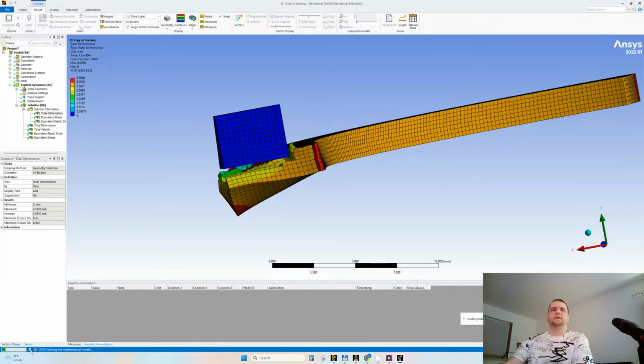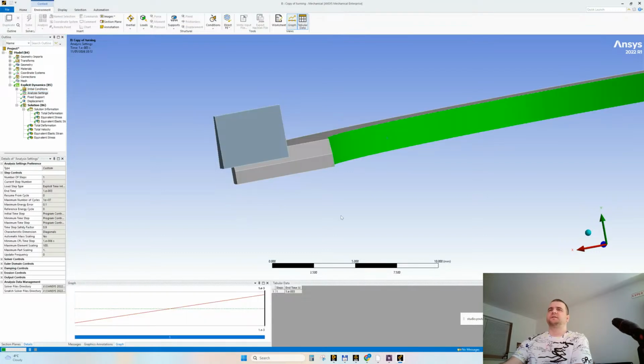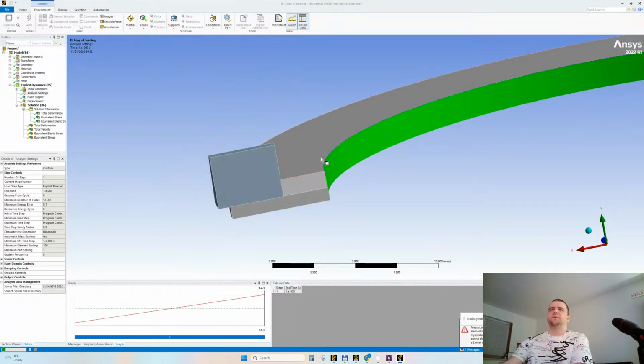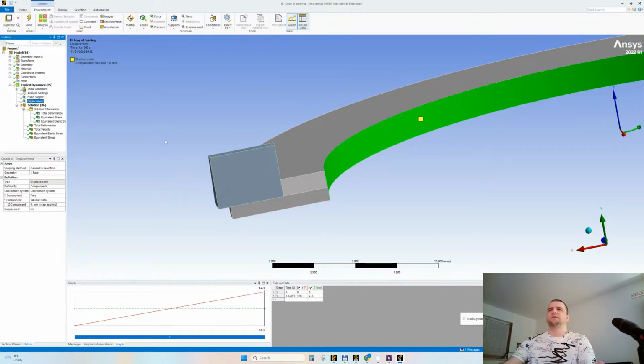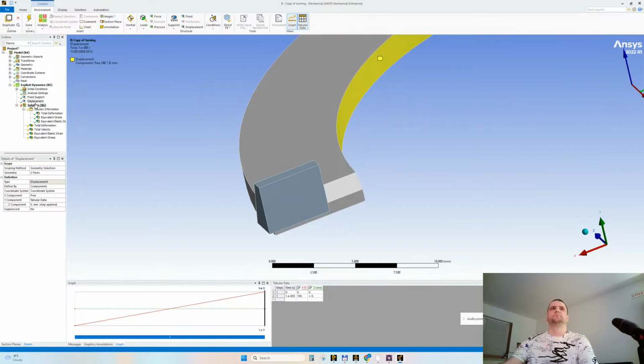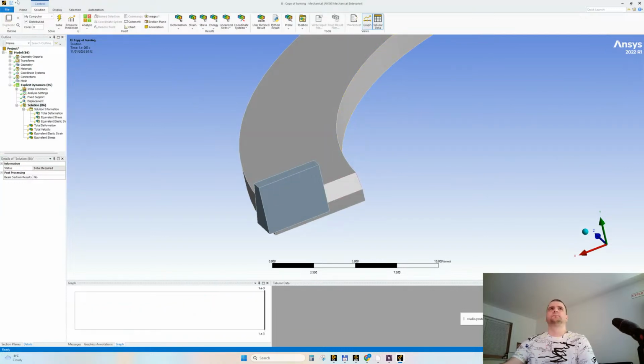When displacing only from this side, it impedes, it decreases the stiffness of the workpiece. This is why I think we can leave it and also add this face with Control pressed, apply. Save and solve.